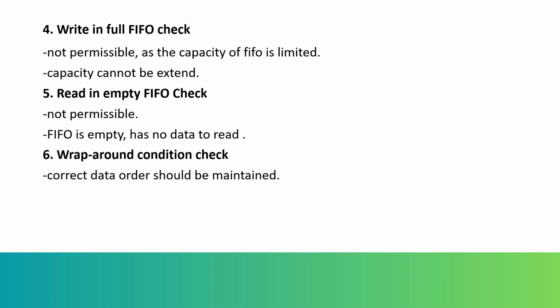For the wraparound condition, we have to check that when our read pointer or write pointer is at the last position of our FIFO, then for the next write and read operation, it should get back to the 0 index.